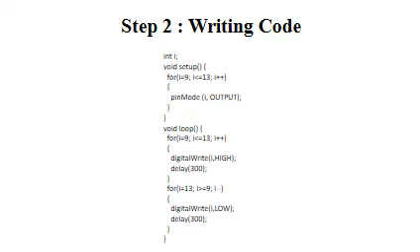In the first iteration, the value of I will be 9 and it will increase by 1 in the next iteration, and in each iteration the pin mode function will execute for the specific number of pin that will be sent to the output. Then in the void loop part, 2 for loops are written. One for sending high voltage to pin numbers sequentially and another for loop sends low voltage to the pin numbers to turn it off. There are 300 millisecond delay in both loops.